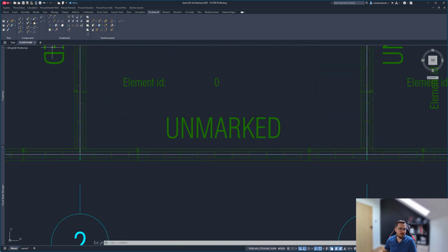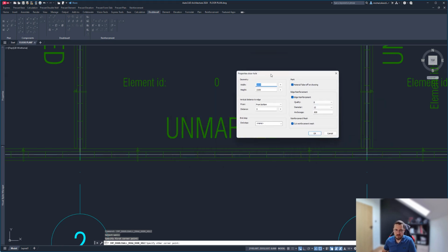What I will do is also create openings, because that might be of interest to you. There are a couple of different ways to create openings. There are rectangular openings here, circular openings here, window holes and door holes. So I clicked on the door opening, I clicked on this wall, and I'll just start placing an opening of some dimension, because it doesn't really matter what the dimension is on screen, since you can still fix it here. For example, make it 2000, right? So that's good. And I can specify the spacing and then the exact placement of that.